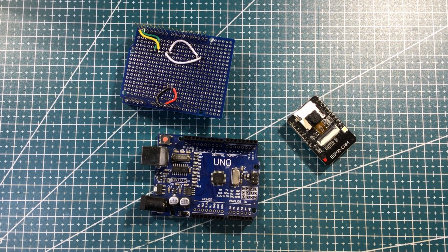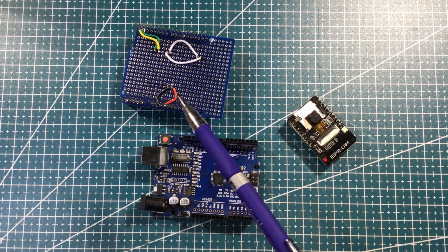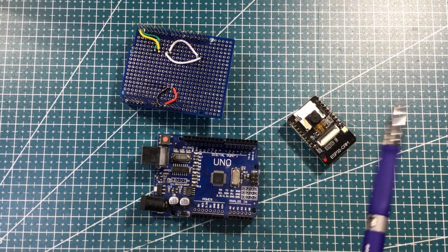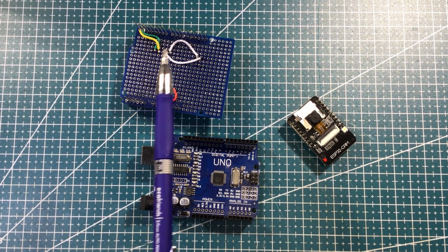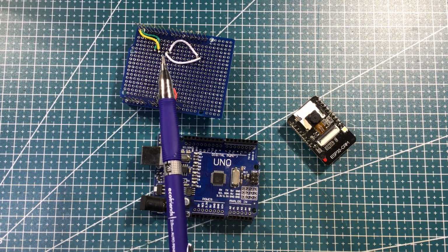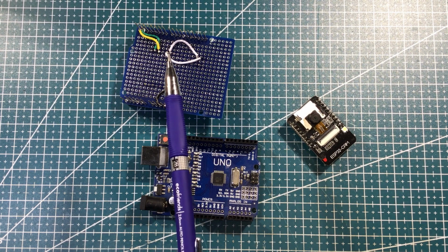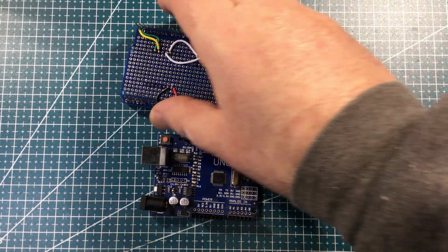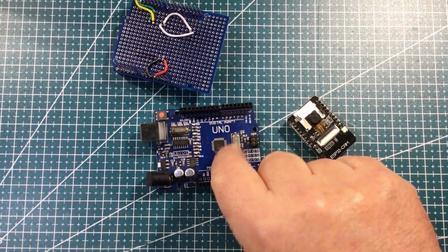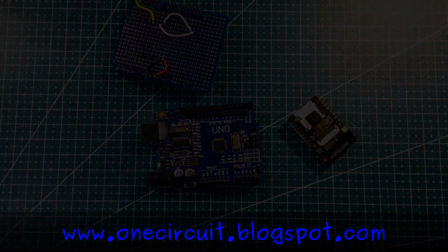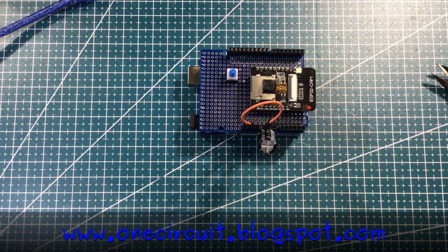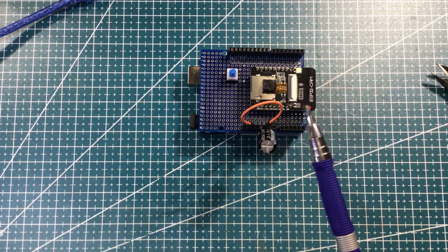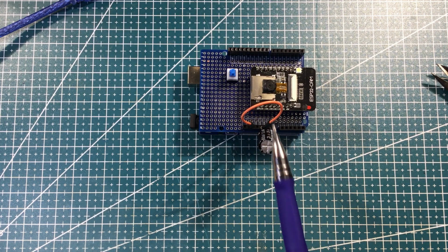All right, so without going over the boring bits too much, I did have these the wrong way around to start with. Everything else went pretty well. There's my TX and RX lines, and here are my lines from IO0 out to the button and back to ground. So all we need to do is to assemble it and program it and hope that nothing blows up. A couple of things which I didn't hardwire in are the wire between reset and ground and the capacitor. So I've just shoved them into the respective headers there.